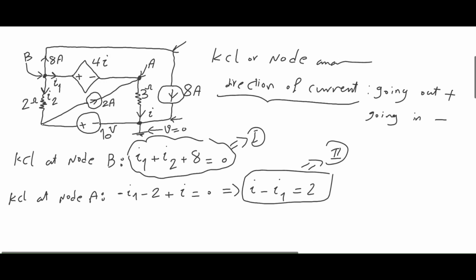It shows that if I were to write the voltage of this node over here, it's 10 volts. Why? Because the reference point is right across this voltage source. So if this negative polarity is 0 volt, this positive polarity has to be 10 volt over here. So I know that this voltage is 10 volt. Let's look at this voltage here.